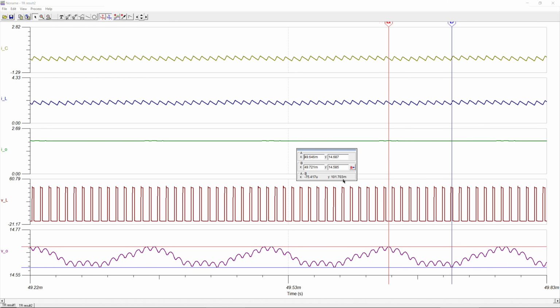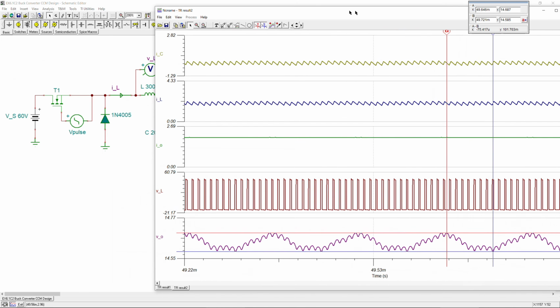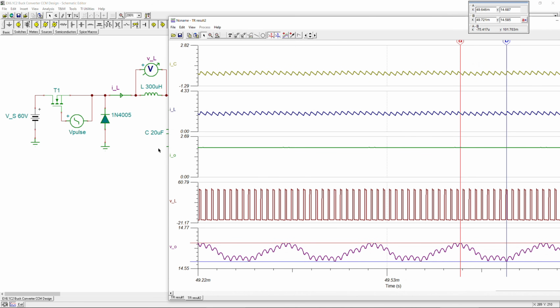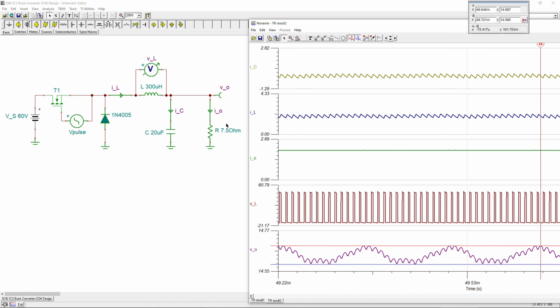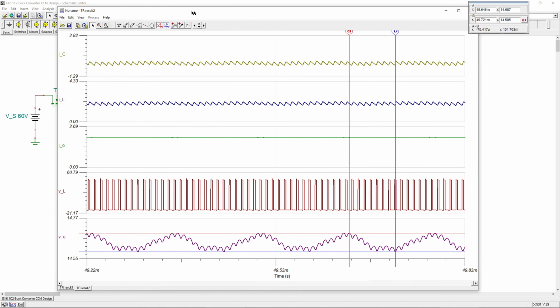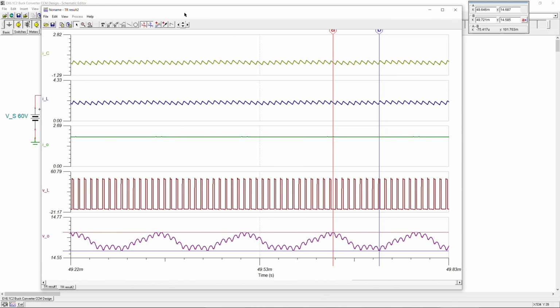Alright, this was our discussion about the buck converter in the open loop configuration. We have discussed how we can calculate the component values, the capacitor, inductor, and also the resistor we need as a minimum for our output voltage and output current specification. We also have tuned, and specifically looked at in TI SPICE, that we need to adjust or increase the capacitor value we have originally calculated to get the required output voltage ripple. If you have any questions about this, please let me know. I will try to answer them as soon as possible.